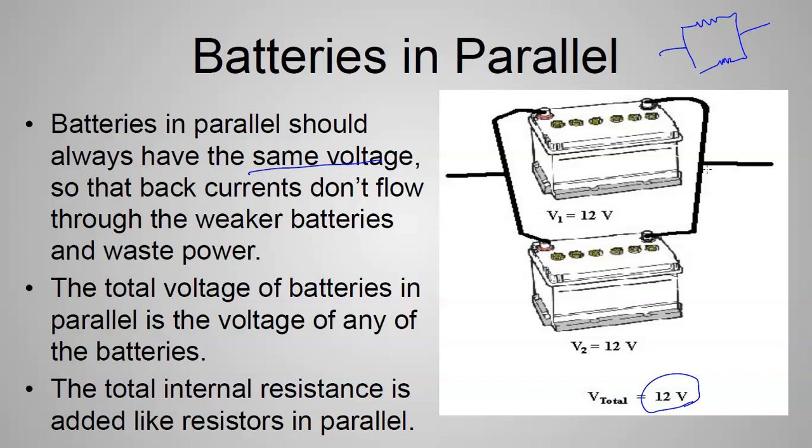Of course, you could have some mix of series and parallel. Let's say that you were using golf cart batteries, which are usually 6 volt. So I could put 2 of those in series, and that would give me 12 volts right there. Maybe I could get a whole bunch of these things for cheap somewhere, and I wanted to do that.